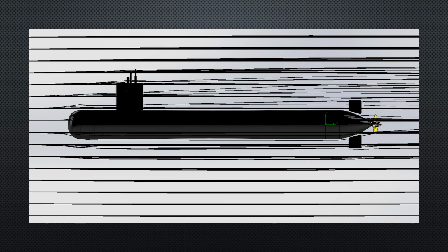This is a photo of the flow trajectories shown without the arrowheads, as well as decreased line thickness. This shows how the fluid is flowing over the model in just a little increased detail. You can also now understand why a large computational domain is vital. As in the previous photos, if I didn't have a large computational domain, the vortices would not be there because they just wouldn't have enough volume to be able to form, and the flow in this photo wouldn't be able to manifest itself because there just wouldn't be enough volume for it to be created.